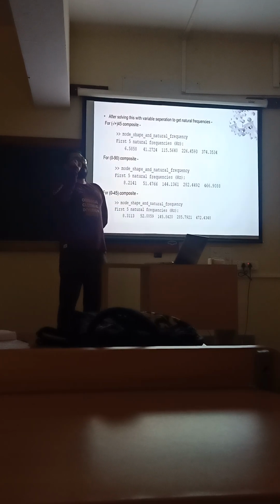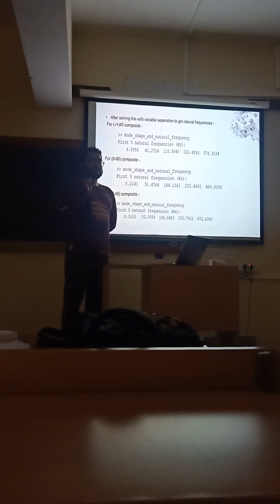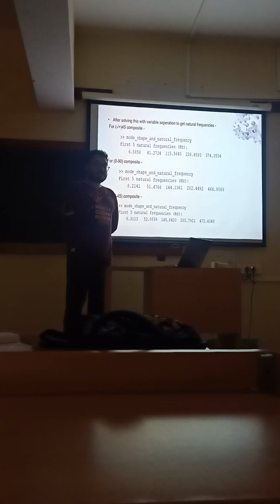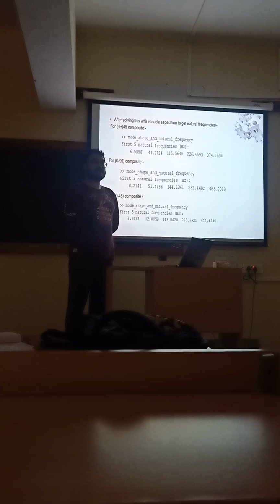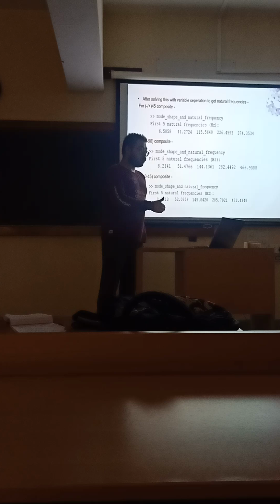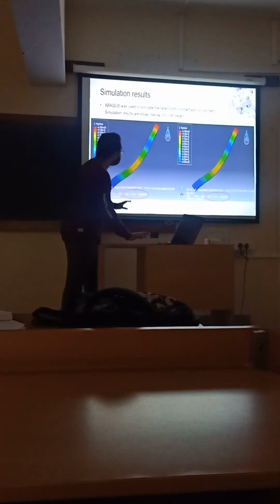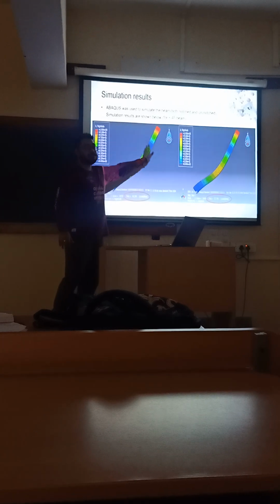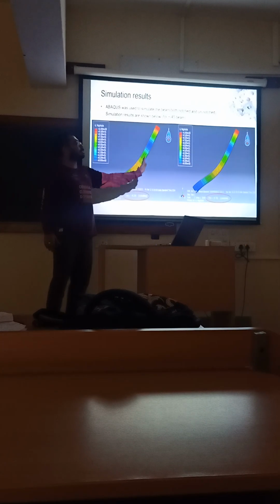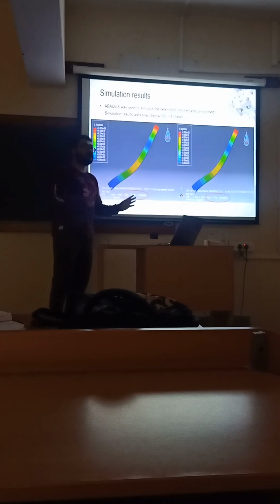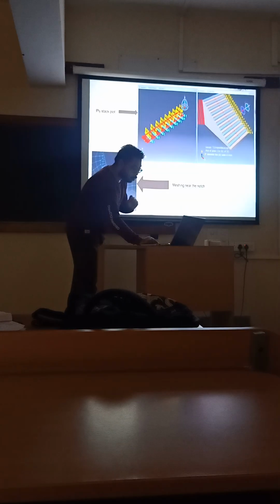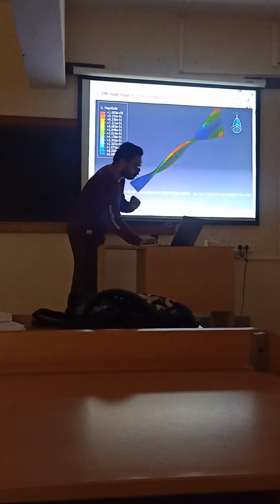If you look at cracks, what is the influence of a crack in a structure? Cracks induce local deformation, local problems in a structure. Now vibration is a global phenomenon. If we look at the lower modes, let me show you some pictures. This is the second mode. You can see the mass distribution or the geometric complexity of this mode shape is not very much compared to, look at the fifth mode.